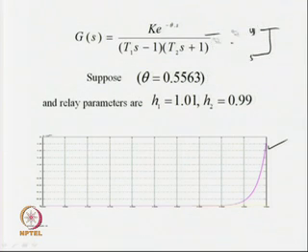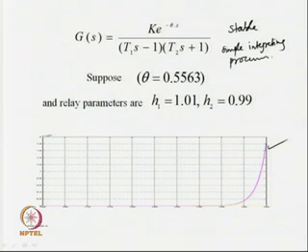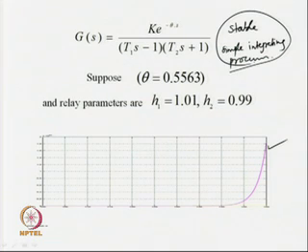For the timing, we should concentrate on this fact that, unlike stable and simple integrating processes, one cannot guarantee stable limit cycle output from an open loop unstable system. This fact is to be taken care of when dealing with unstable systems, and unless it is possible to obtain stable limit cycle output from unstable systems, it will not be possible to identify the transfer function model parameters of the dynamics of an open loop system.